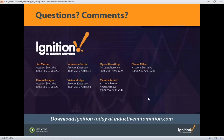I would say probably. I'm unfamiliar with those systems specifically and how you interface into those. We support all the standard industry interfaces. So we have OPC and OPC UA and DA. So if we don't have a communication to a device, you can use either a Kepware or somebody like that, an OPC server, and Honeywell might have their own, and interface with it.